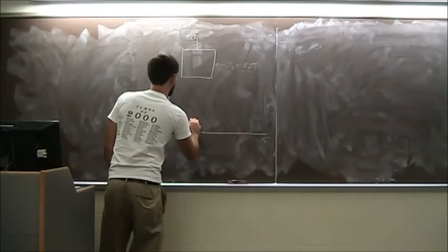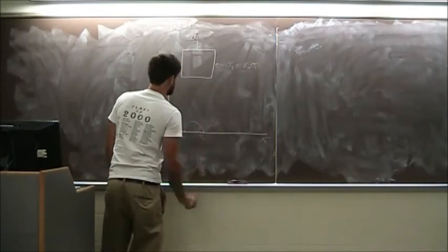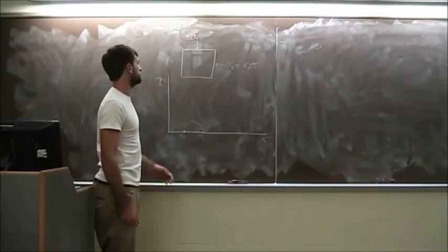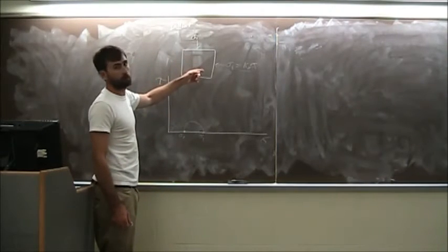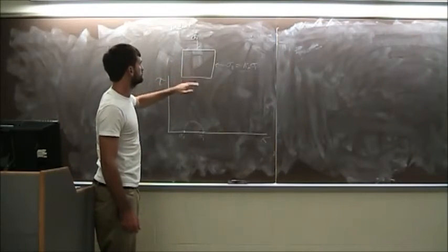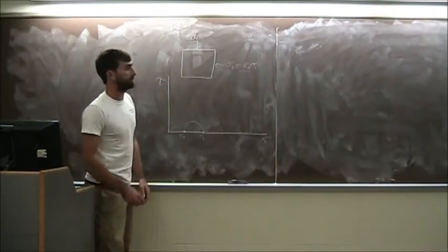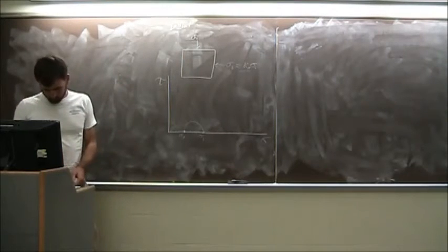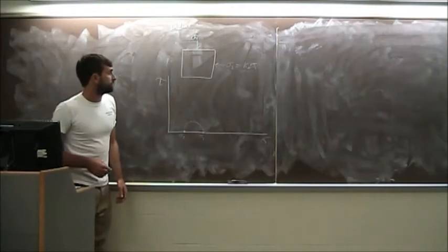And you've got some Mohr circle. What you're looking at is sigma 1 and sigma 3 are principal planes because there's no shear stress on either one of those planes at this time. So that's your initial state.